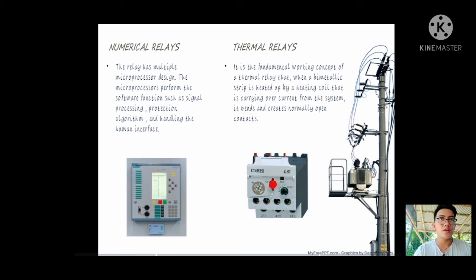Next is the thermal relays. The basic fundamental working concept of a thermal relay is that when a bimetallic strip is heated up by a heating coil that is carrying overcurrent from the system, it bends and creates normally open contacts.